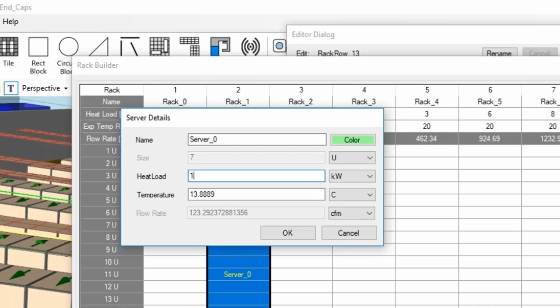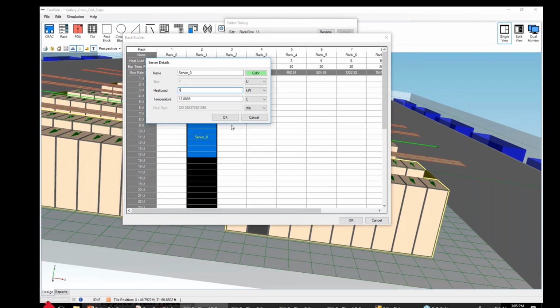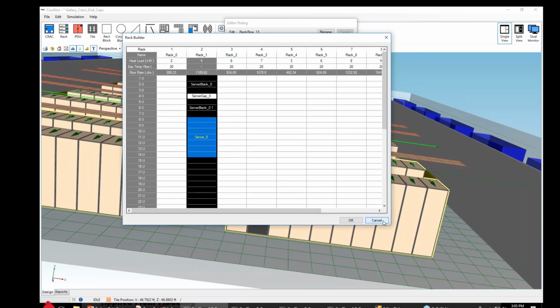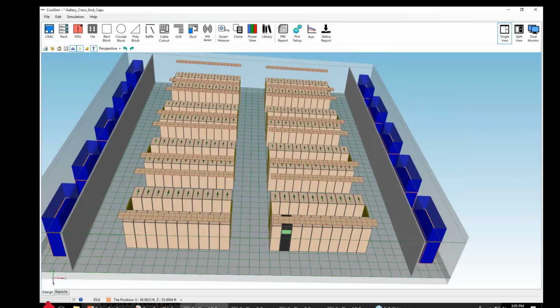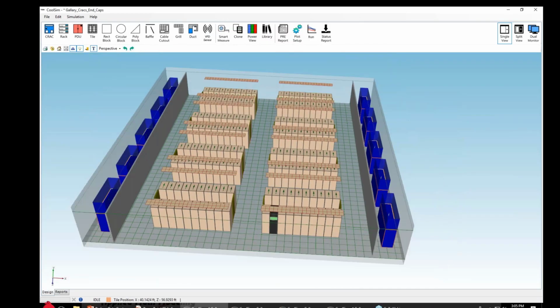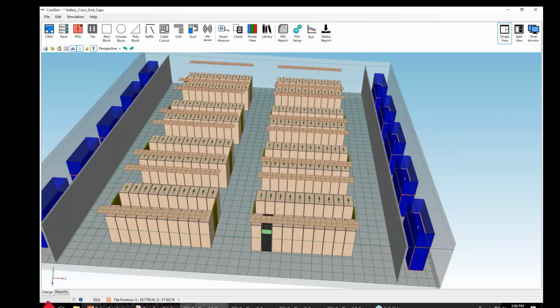How significant is static pressure to supply VFD performance? As I mentioned, static pressure I don't think is a good proxy for what's going on in the data center. It's my own personal experience, but as I mentioned, where do you put the pressure sensor? And how tight do you control it? It's a little bit like measuring carbon dioxide in a room to understand how well the humans are doing. Humans don't breathe carbon dioxide, so it's a proxy. Here, pressure is a proxy for inlet temperature. So what I'd rather do is just measure inlet temperature and drive it that way.